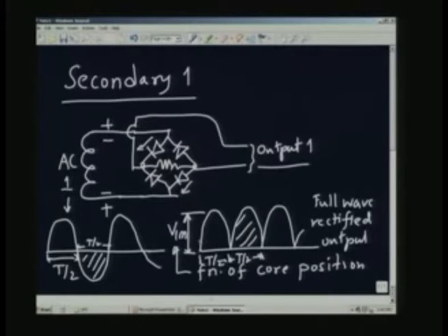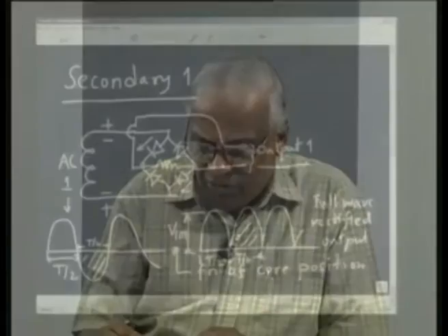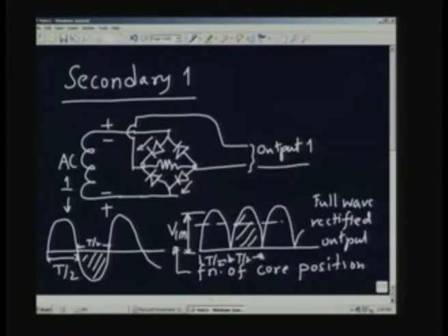So if I pass this wave through a filter which is going to remove all the high frequency components, what you will get is only the mean value coming through, the mean will pass through. So the average value will be something like this, this is the average, or V1 DC. V1 DC is going to pass through, the rest is going to be removed.